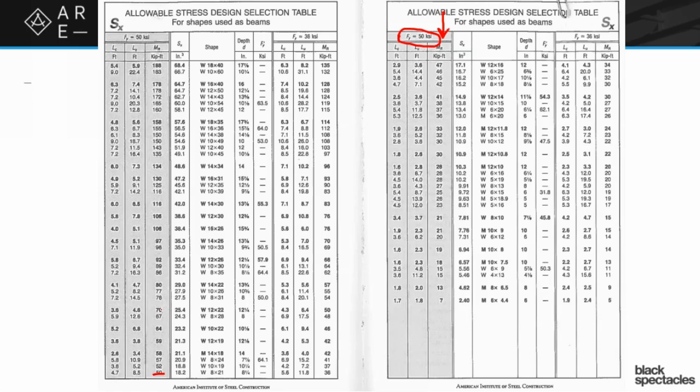And so if it's a higher weight per linear foot, it costs more. That's straightforward. Unless it is specifically asking you about height issues, the choice will always be to go with the lighter weight example for the wide flange, as long as it's not outrageously different in terms of height, but it's always about that lighter weight.